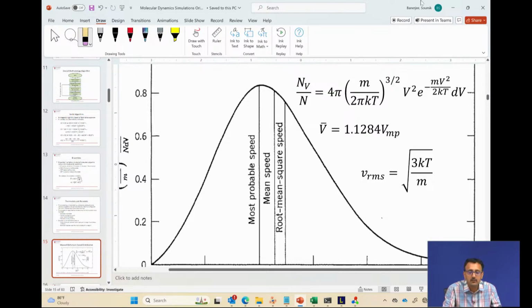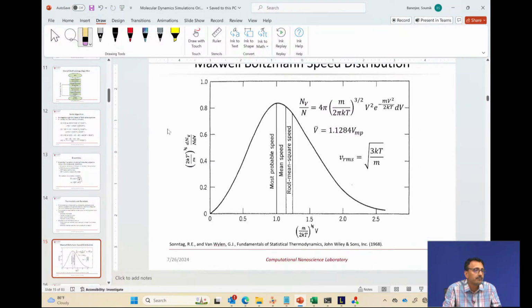Sir, for a very highly unsymmetric structure like a triclinic lattice, since it is considering the center of symmetry in the picture, in that case things change a little. The centrosymmetry, as far as I understand, is only defined for BCC and FCC crystals, that is the cubic system. Right. For monoclinic type crystal structures, there are many compounds found as such. In that case, the approach will be completely different. I think so. You will have to come up with an alternate definition.